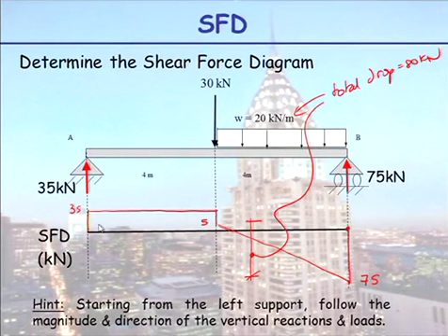So that is why you have zero slope with no load. That's telling you you've got no load acting on there. Your shear force diagram is horizontal. When your shear force diagram is linear, the slope of that line is equal to your load.